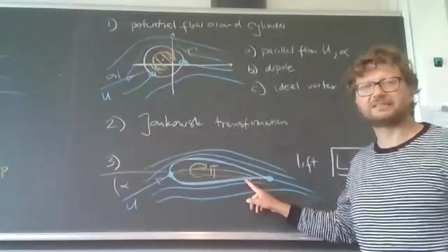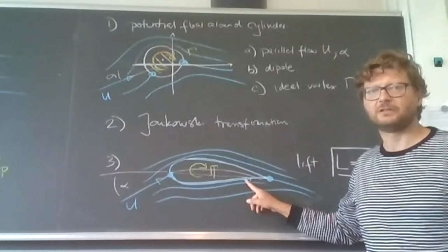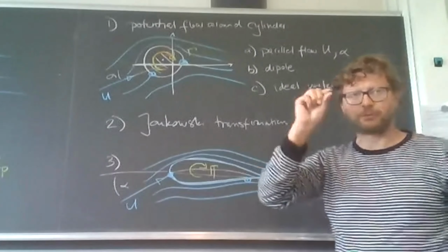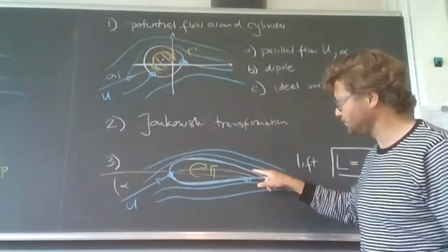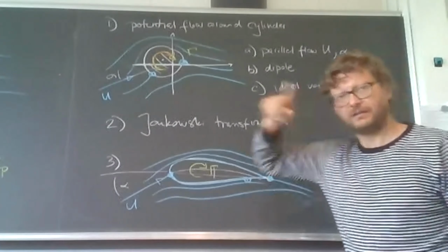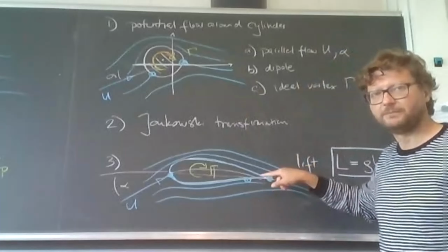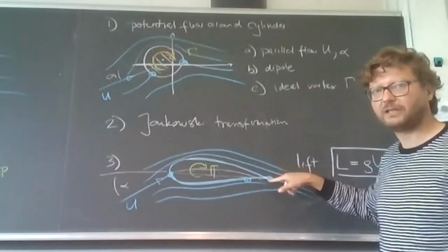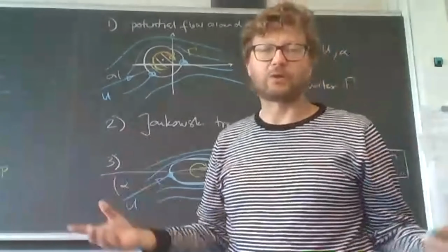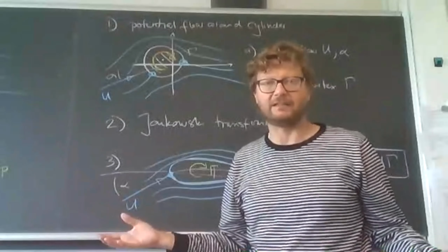If this was the stagnation point, what would this mean for the flow? It would mean that the flow at the trailing edge, which is the pointed edge, would have to go at non-zero velocity around the corner. Because at this sharp corner, we have locally an acceleration going toward infinity, which of course is nonsense and will never happen in reality.